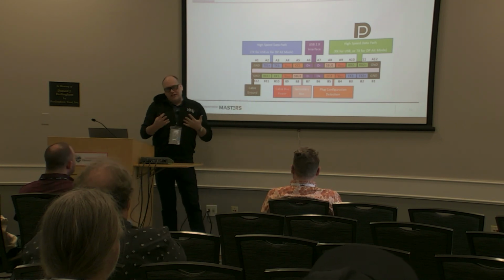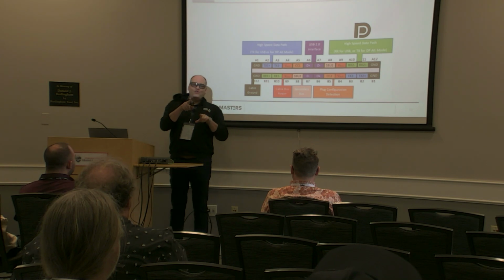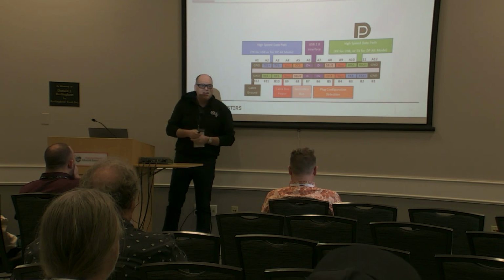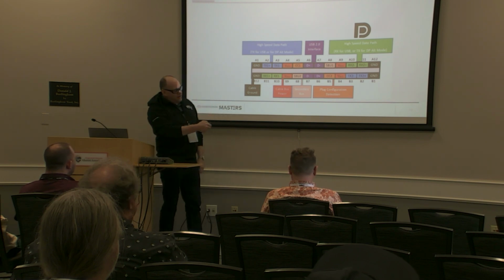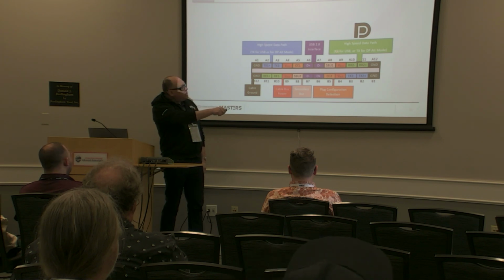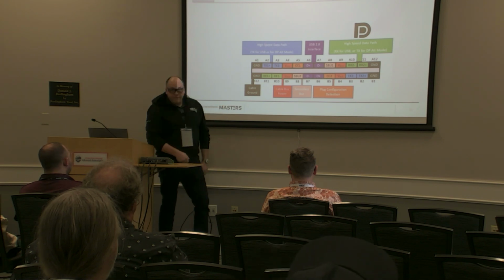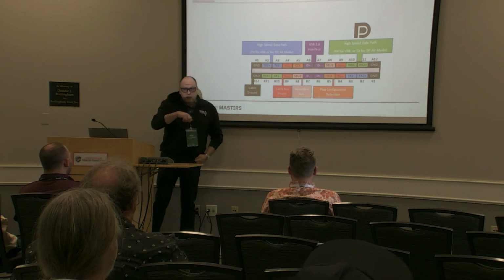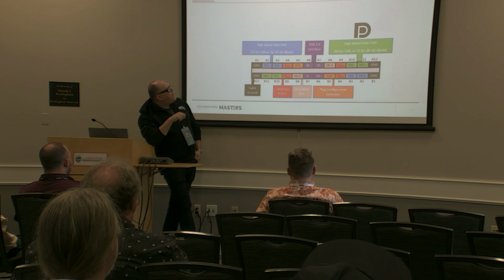That's how it actually does it. There's a pair of pins in there whose sole purpose is to tell the host controller, hey, I'm this way or I'm this way, right? So that's how it identifies our DisplayPort alt mode path, which is here on pins A10 and A11, right? And when you flip it, they show up down on B11 and B10. And then how we have our high-speed path.